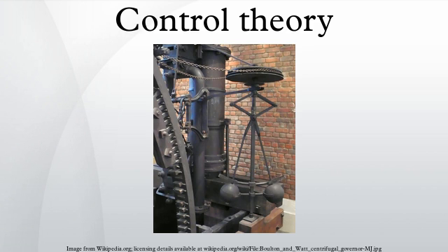Adaptive control uses online identification of the process parameters, or modification of controller gains, thereby obtaining strong robustness properties. Adaptive controls were applied for the first time in the aerospace industry in the 1950s, and have found particular success in that field. A hierarchical control system is a type of control system in which a set of devices and governing software is arranged in a hierarchical tree. When the links in the tree are implemented by a computer network, then that hierarchical control system is also a form of networked control system.